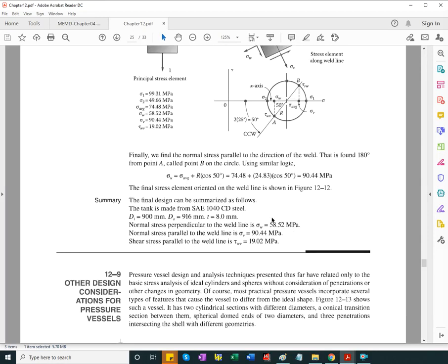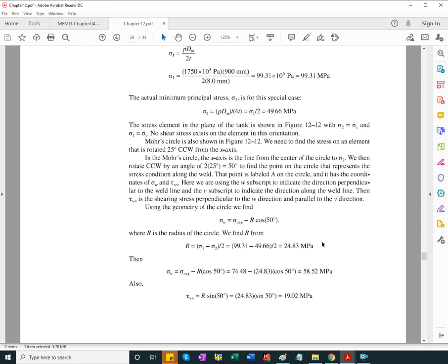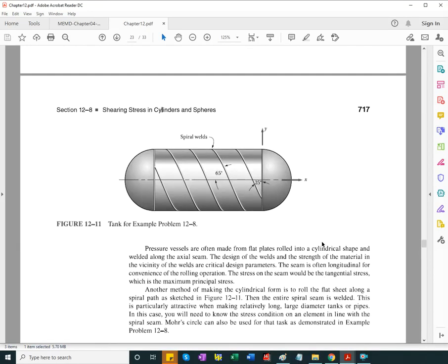Sizing pressure vessels. We look to the basics. In the problem, just to practice on real cases, not just made-up sigma x, sigma y, tau xy values, but rather values coming from careful analysis, we're going to look at pressurized pipes that are also subject to bending and torsion, again in addition to the stresses induced by pressure.